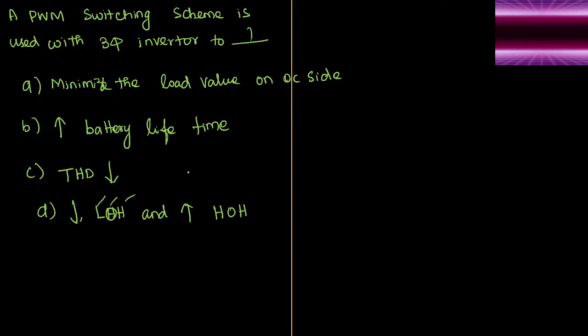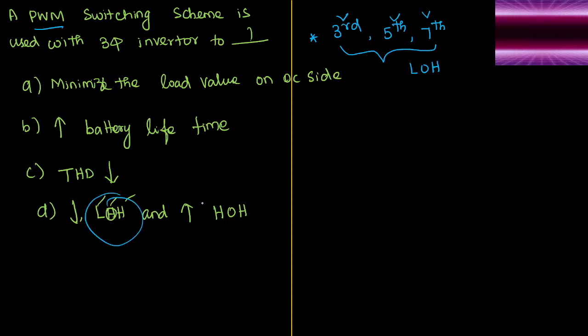Basically, so far what we discussed, why we are using the pulse width modulation technique, I have been telling since the starting. Using pulse width modulation, I told you mainly our concern is third order harmonics, fifth order harmonics, in some cases seventh order harmonics. So we are keeping our attention on the lower order harmonics. Yes or no? The major purpose. Pulse width modulation technique is generally used to eliminate the lower order harmonics only. Since the starting of the lecture I am telling. So when we are trying to reduce the effect of lower order harmonics, the higher order harmonics effect will go off.